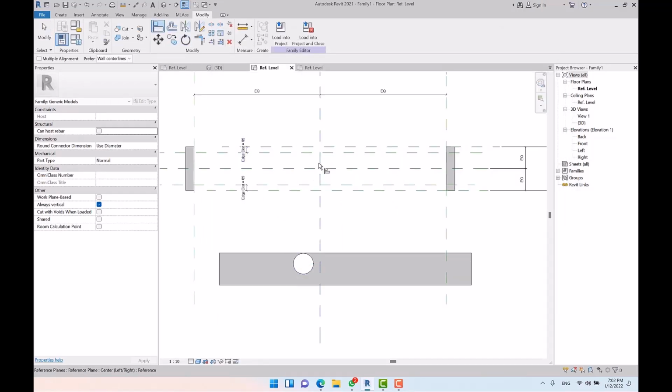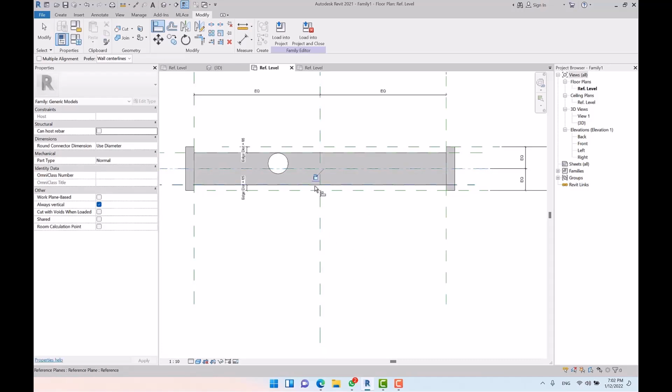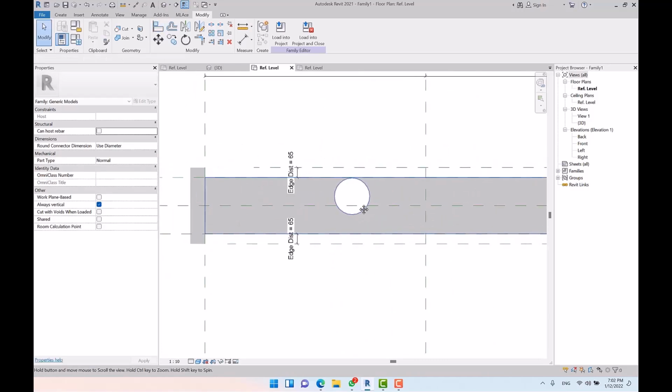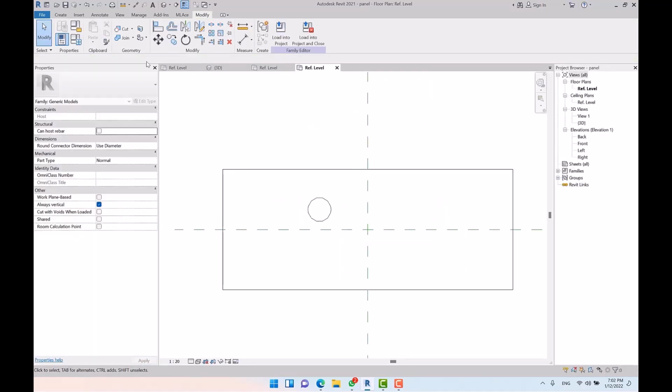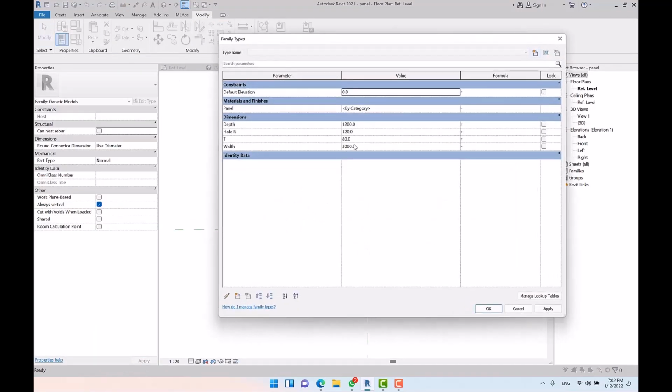Anyway, here we got a problem. Let's solve it. Let me align the extrusion this way with the reference planes. I place it right here and then I lock it. Well done. Actually, here I should control the value of hole radius, since it is not appropriate in relation to the size of the panel. So I open its family, edit family, then in the dimensions. Later I will talk about the conditional formulas in future sessions.